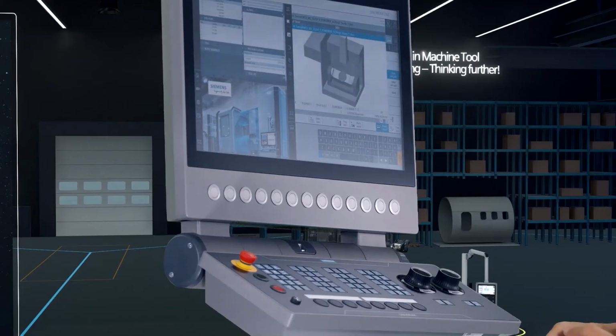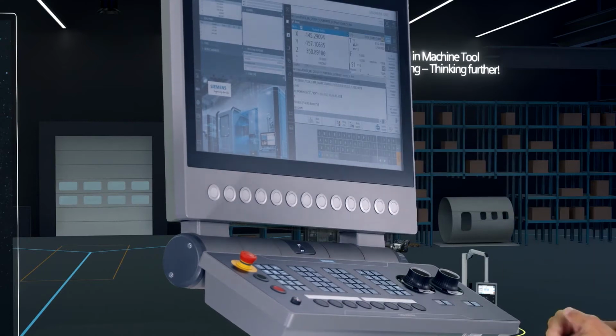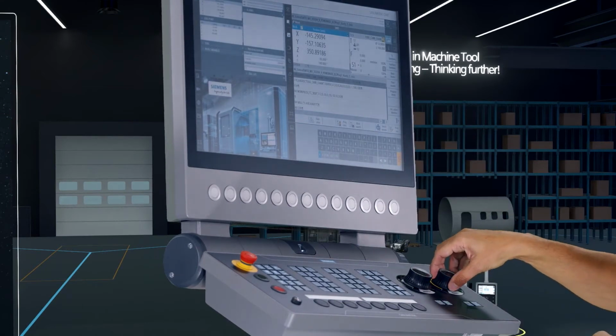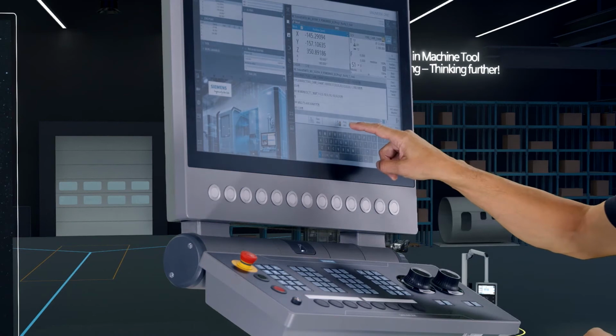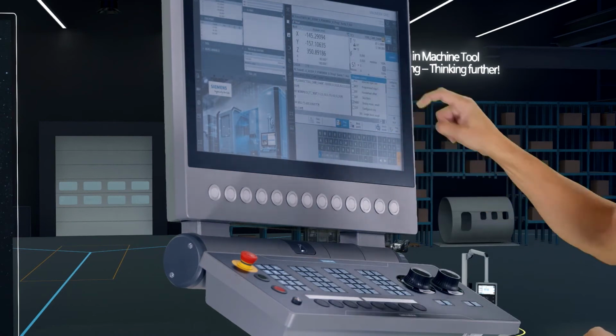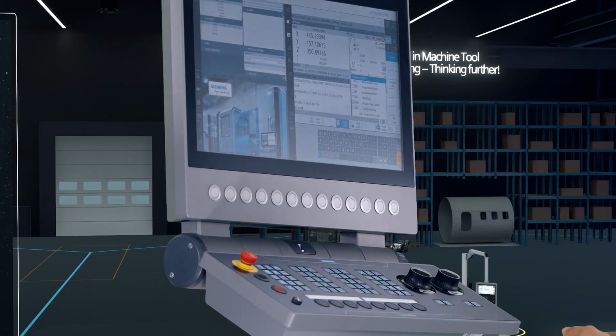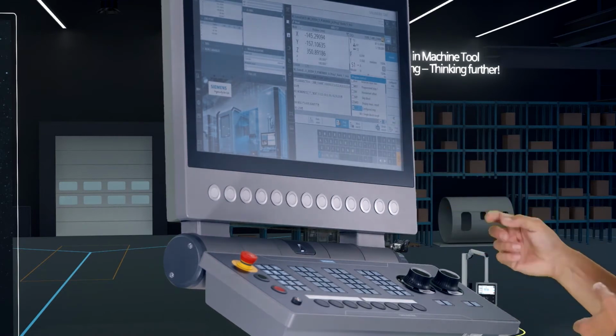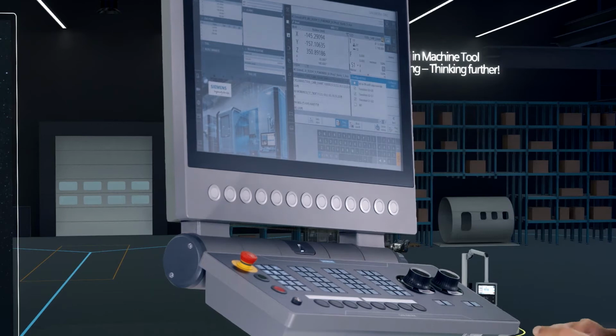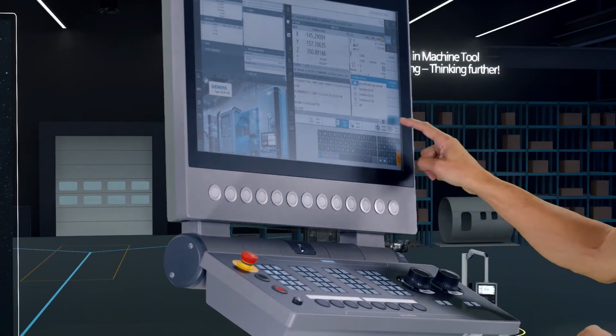When I execute this part program, I have the possibility, in combination with the new PowerRide, to adapt via the function configured stop under program influence, where I can decide when the machine stops and starts. The configured stop situation could be defined via transition G0, G1, G0, G0, and G1 and T0. And on top of it, also with additional functions like M functions or subprograms.